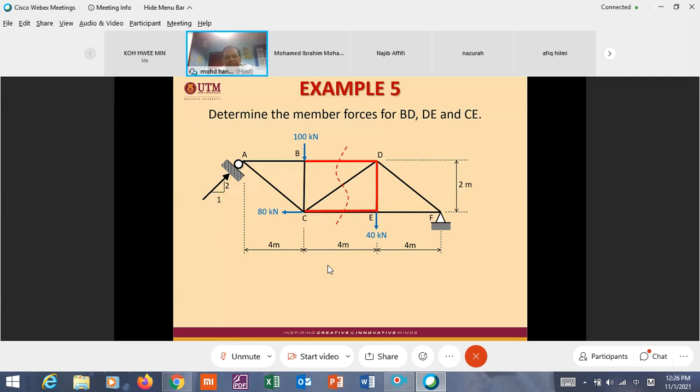So what we can do is we need another cutting. We need another step. Cut another one. Cut 3 members, not 2 members, 3 members, because we have three equations. When you have three equations, you have to cut three unknowns, or three members. So this one three, this one also three.